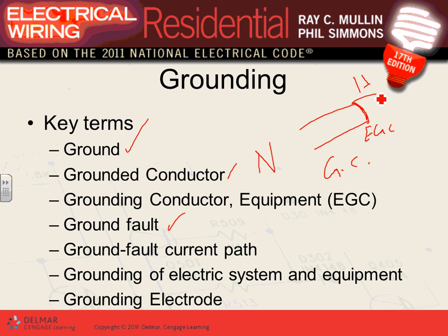Ground fault path is the path through the hot, through the means of connecting these two together, back all the way to the source. That's called the ground path. When you have a ground fault, guys, you want the ground path to be interstate highways, not Minneapolis alleys. Big, fat, so the energy will go so fast and the circuit breaker will trip so fast. Again, we will be talking about this, guys.